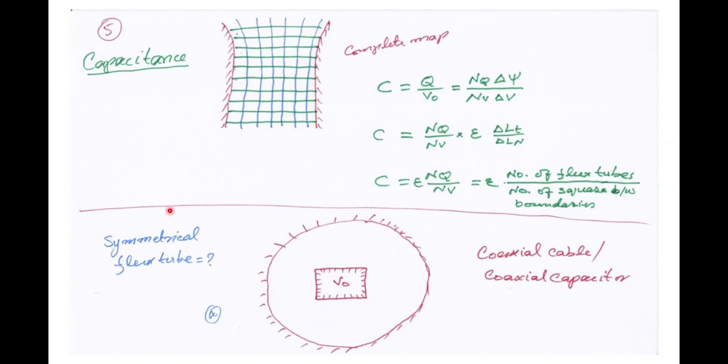How to calculate the capacitance using curvilinear squares in between the conducting boundary. So look at this figure. The red curve represents the conducting boundaries, and we have filled the space between the conducting boundaries into a large number of curvilinear squares. The green line represents the streamline, and when we consider two streamlines, that represents a flux tube. The blue line represents the equipotential surfaces.